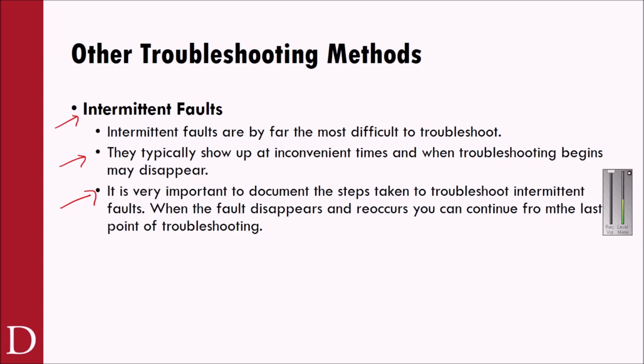The other thing I've seen people do is use things like digital multimeters, digital storage scopes, and different digital test equipment that you can actually hook up to a circuit and have it log data. So you could put it onto a circuit and take a voltage reading every 30 seconds or something like that. So you might discover that, oh, you know what, at 2 o'clock in the morning every night we get a little surge in electricity, or something happens that maybe is causing this because it's lining up perfectly with what's going on here.